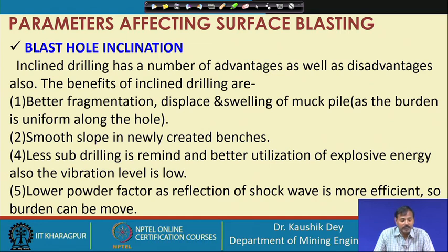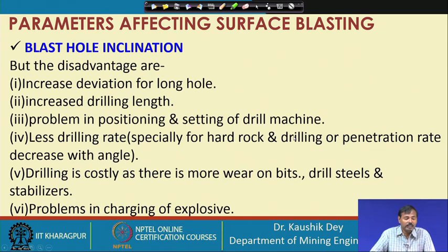The benefits are that inclined drilling gives better fragmentation and throwing of the rock, it gives a smooth slope in newly created benches, the sub-drilling requirement is less, and better utilization of the explosive energy is possible. Designing is also easy because the burden always remains the same along the bench face, and powder factor is also low because the reflection of the shock wave is more efficient in this case.